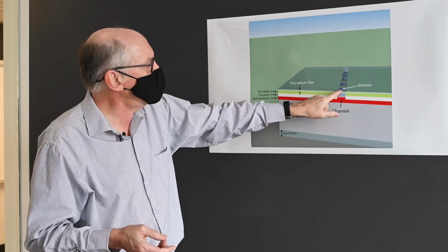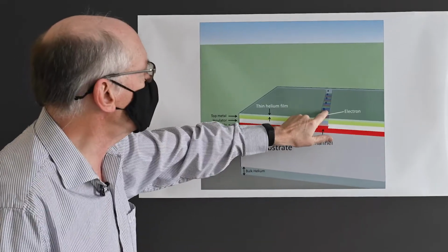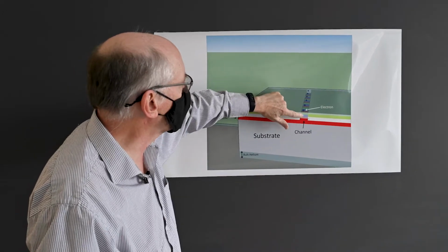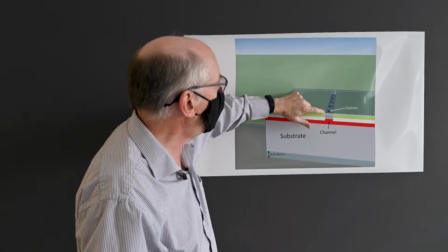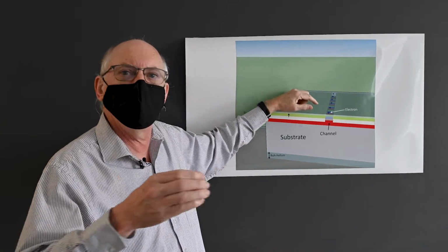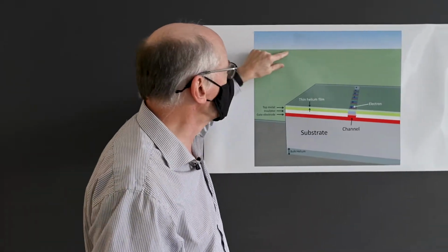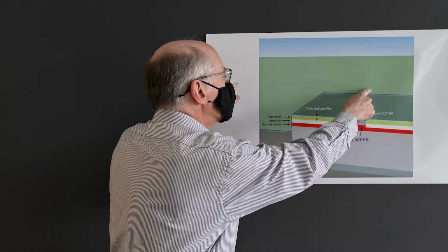And now what we can do is trap the electrons with a voltage applied to these gates. And I have this designed as a CCD. I have 3 different voltages, the red, the blue, the green. We can now move these electrons along that charge-coupled device there. Now, that's the simple picture of how these devices work.